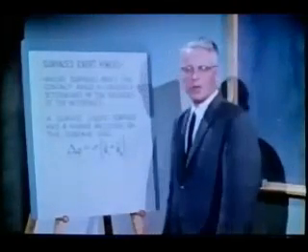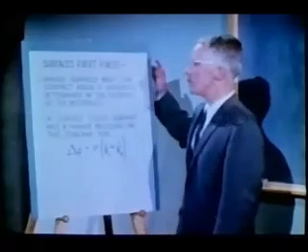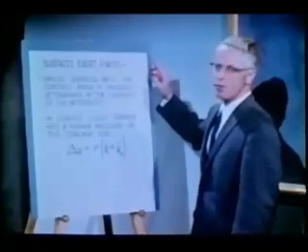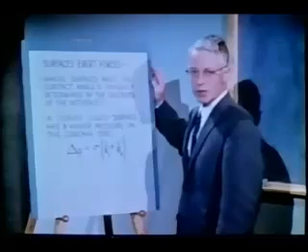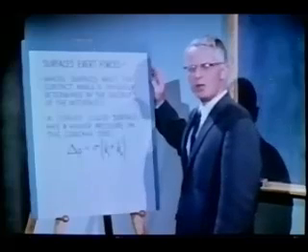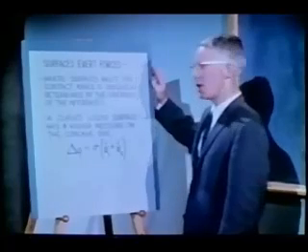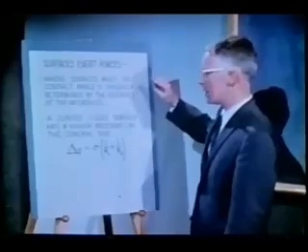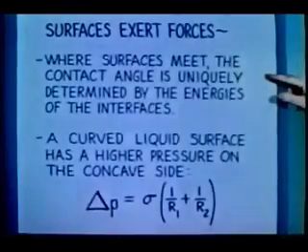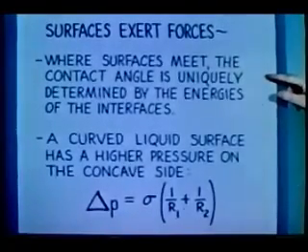If we accept this hypothesis that surfaces exert forces, we find that there are three boundary conditions expressing these forces that need to be used with the continuum equations of fluid mechanics. We've just seen examples of the first, that where surfaces meet, the contact angle is uniquely determined by the energies of the interfaces.